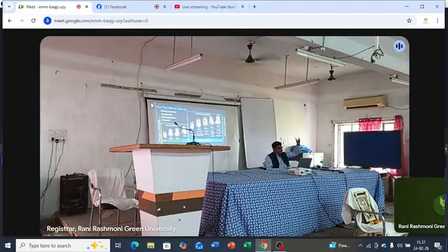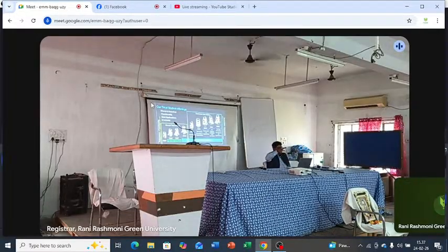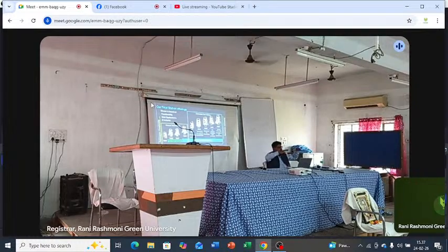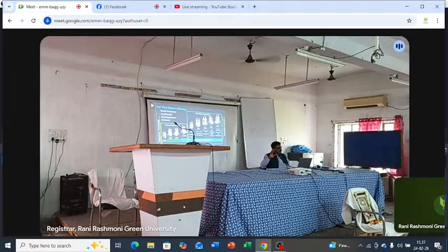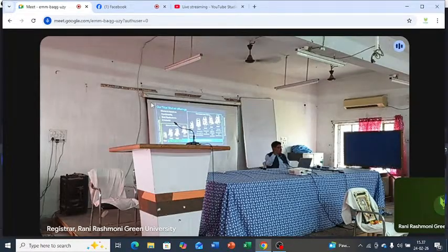Suppose there is a dam wall or a load on a bridge, which is probably sinking, or there is some deformation taking place, and you need to monitor the movement of that particular object. So you can put prisms on different parts of the structure and place a total station a little bit away. What does that total station do? It measures all the prisms and stores the data into its memory.